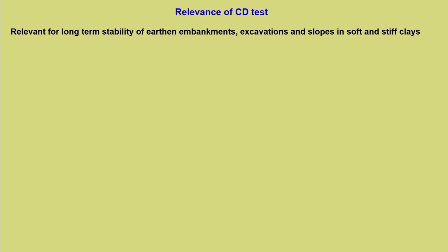Now, what is the relevance of the CD test? The way we have discussed it for the CU test, more or less it remains the same. In fact, those conditions that we discussed in the CU test are more appropriate for the CD test in terms of its long term behavior. So, it is relevant for long term stability of earthen embankments, excavations and slopes in soft and stiff clays.